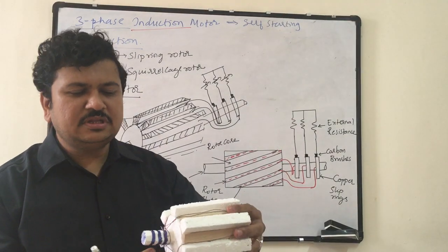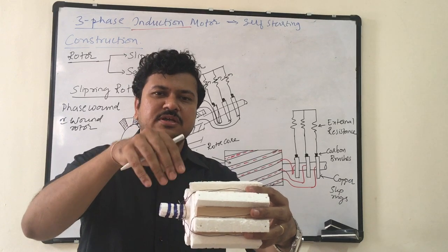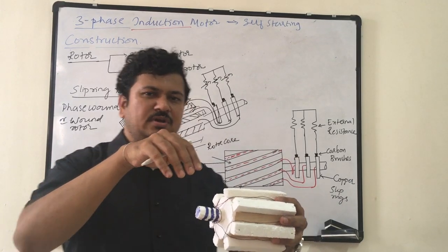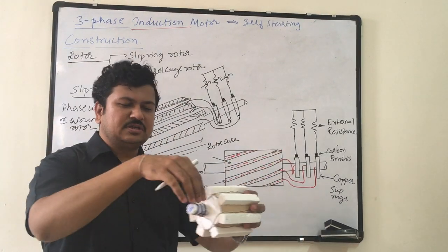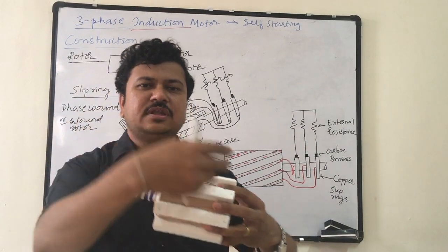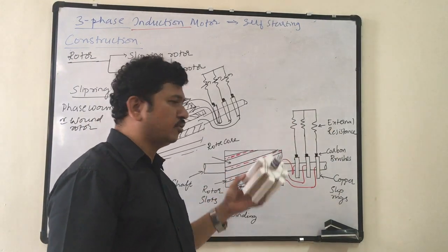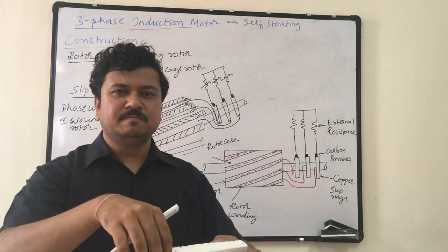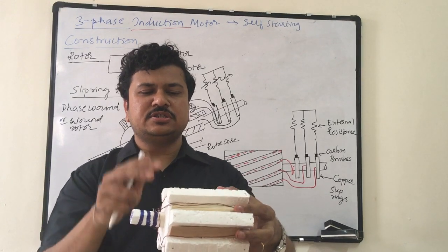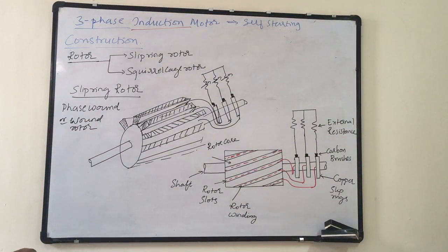And because I am using these slip rings, see, these rings are slipping on the brushes, hence it is called slip ring. Okay, so these 3 slip rings are connecting my external 3-phase resistance to the 3-phase winding which is rotating. So stationary body is connected to rotating body through slip rings. Because this structure is used, this is called slip ring induction motor.